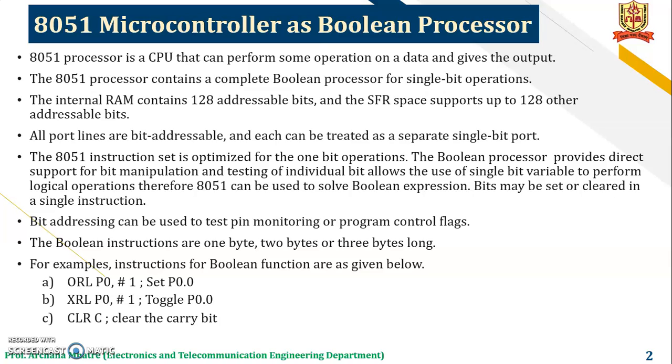The internal RAM contains 128 bit addressable bits and the SFR space supports up to 128 other addressable bits. All port lines are bit addressable and each can be treated as a separate single bit port. Bit addressable means the programmer can individually set or reset a particular bit through programming. The 8051 instruction set is optimized for 1-bit operations.